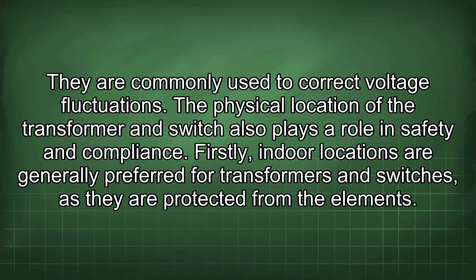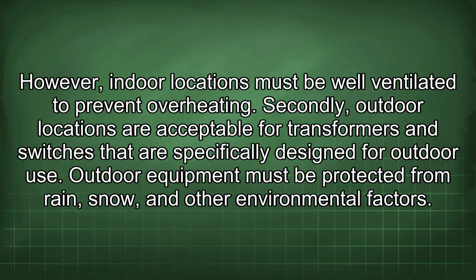Firstly, indoor locations are generally preferred for transformers and switches, as they are protected from the elements. However, indoor locations must be well ventilated to prevent overheating. Secondly, outdoor locations are acceptable for transformers and switches that are specifically designed for outdoor use. Outdoor equipment must be protected from rain, snow, and other environmental factors.